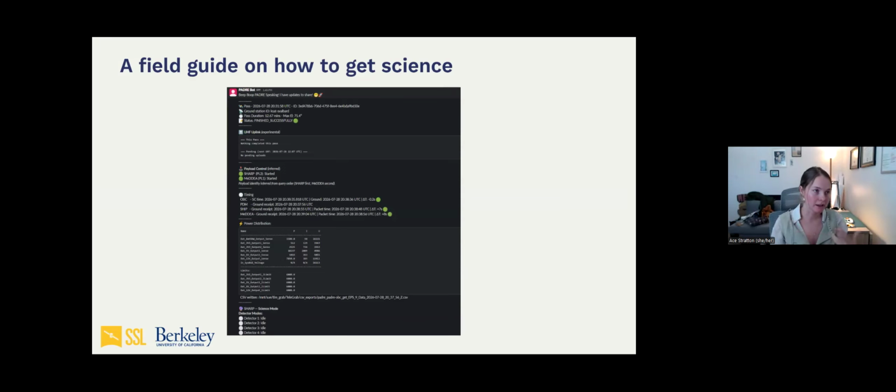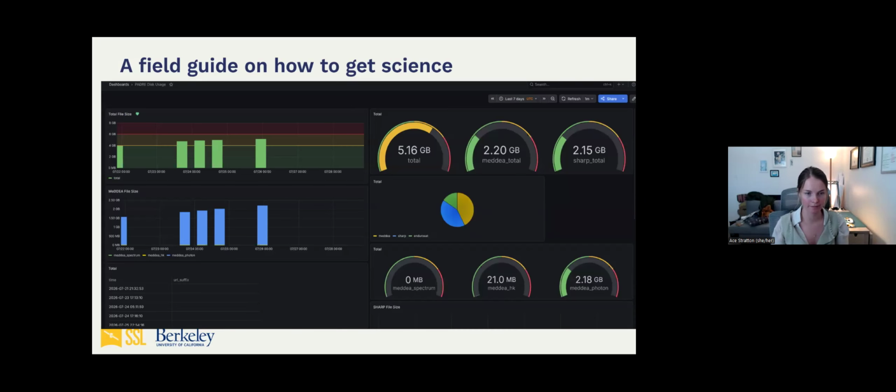Once you're there and you're getting commanding done, the next thing I'm doing all day, every day is making sure it's healthy. At any hour of the day, it's my job to make sure that every time we get this report, this is like one of 8 screenshots I could have gotten of the report I get every hour, I see: are you fully charged? Are you still charging? Do you have the correct time on board? Is the temperature okay on board? What are my detectors doing? What states are they in? What's going on? And you would think, okay, that's not so bad. Surely things don't happen very often, right?